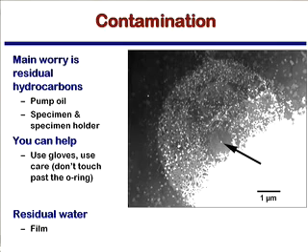The other thing that we worry about is water, and in fact, one of the other nice things about just getting rid of film in the system is that the film is a piece of polymer. It always has some water absorbed on it, and so if you just remove film, you find that your system's cleaner and easier to pump out, okay? Usually when you're storing your film, you store it under vacuum, but you have to take it out of that vacuum and move it over, and so it does, again, introduce problems with your vacuum. So again, the message: you have to get rid of the air, have to get rid of the ions so that the electrons can travel through vacuum, but more important, you really want to have a decent vacuum so that you don't interfere with your imaging of your sample.